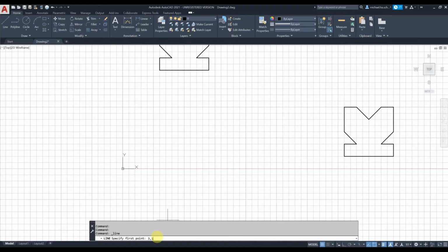I put down here, press enter. For polar coordinates, as I mentioned, let's do add sign, so it's going to be relative. The length of the line would be 4 units less than 0 degree. So it's not less than, but it's a symbol to define the angle with respect to positive x direction. So press enter. As you see, we define the length and the angle.